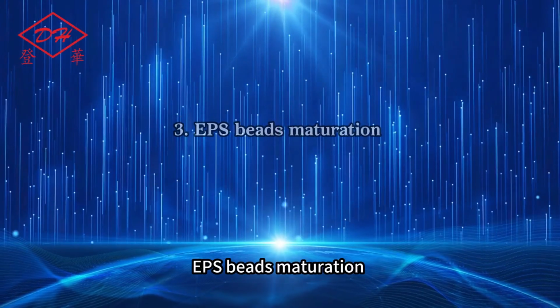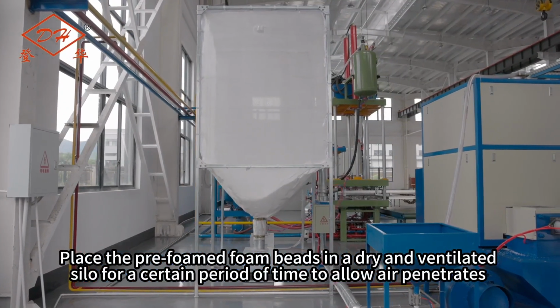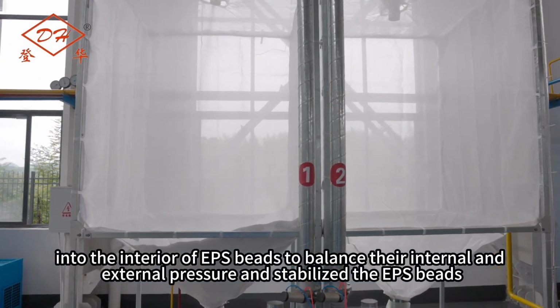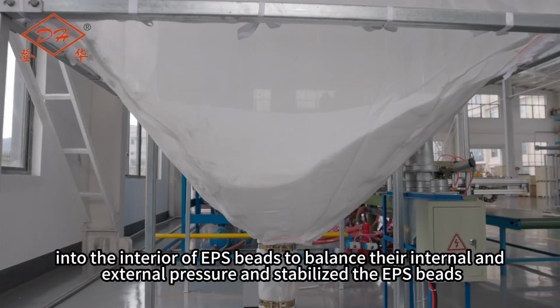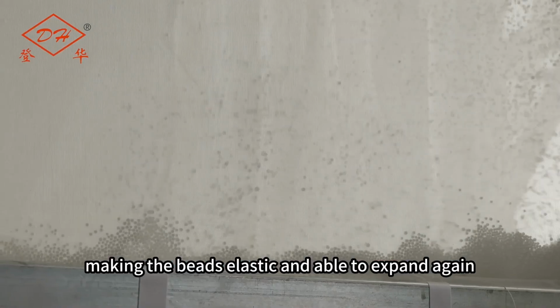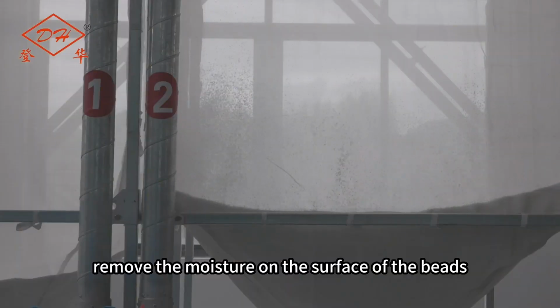Third, EPS beads maturation. Place the pre-foamed foam beads in a dry and ventilated silo for a certain period of time to allow air to penetrate into the interior of EPS beads to balance their internal and external pressure and stabilize the EPS beads, making the beads elastic and able to expand again. At the same time, remove the moisture on the surface of the beads.